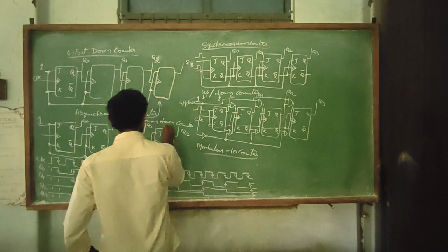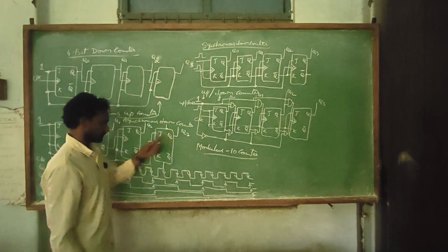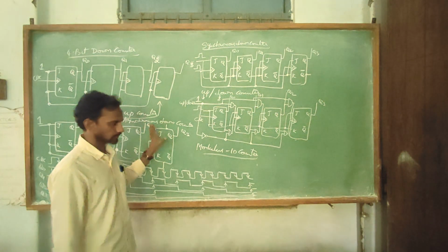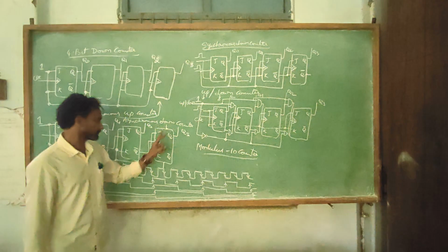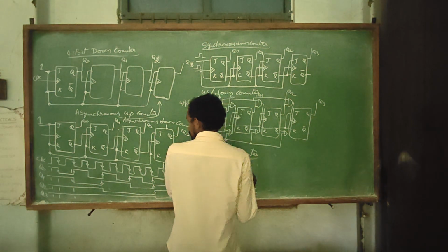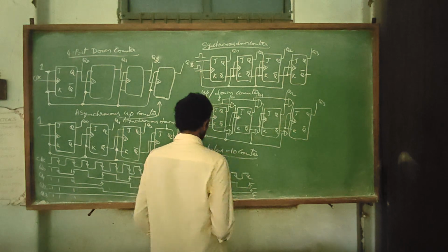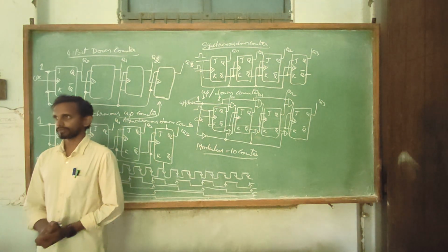So there are set and reset buttons for each flip flop. They are not shown here because they are not used here. There is a set button and a reset button for every flip flop. So now I am going to use that. So modulus 10 counter, it counts up to 9.